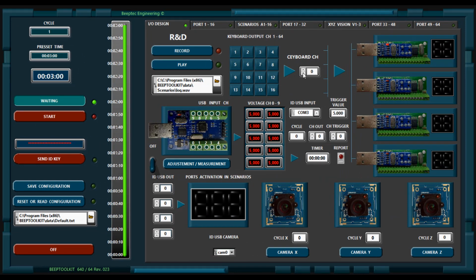When we need to generate a logical unit of one of the 16 channels of the USB output module, first of all, we need to enter an instruction indicating the ID number of this module. If several output modules are used in the project, the channel is addressed in accordance with the ID of the module number specified in the instruction.